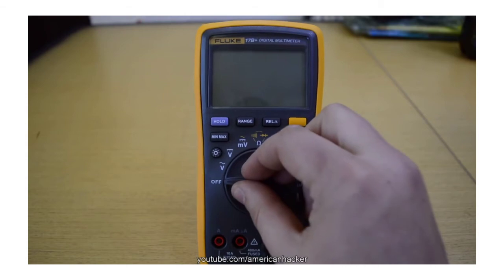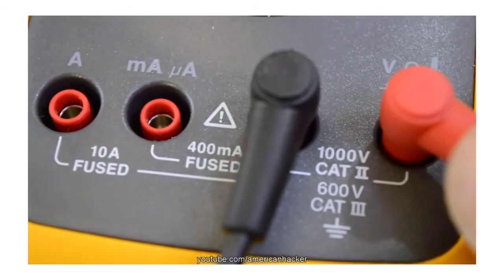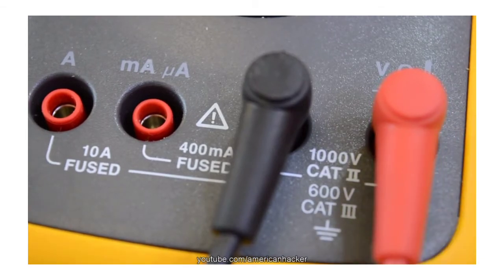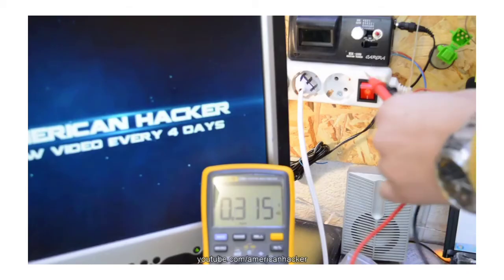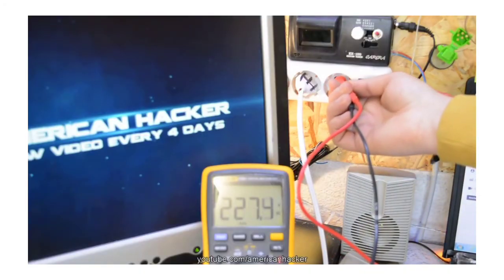We're gonna measure AC voltage right now, so I'm plugging the red probe into the jack labeled volts and ohms, not amps. Set the dial to measure AC voltage. Here I am measuring AC voltage in my outlet, it's 220 volts.